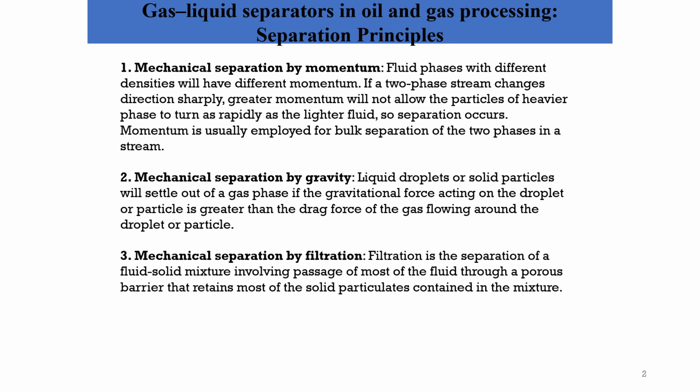And the last one is the momentum separation. In the momentum separation we are referring to separation based on the density of the fluid. So if you have two fluids flowing in the same direction and each one has a different density than the other, and you apply resistance to that flow, what will happen? The heavier one will move slower than the lighter one, or the one that has lower density will flow faster than the one that has high density, and as a result the separation will take place between these two fluids, due to the change in momentum as a result of the difference in density.